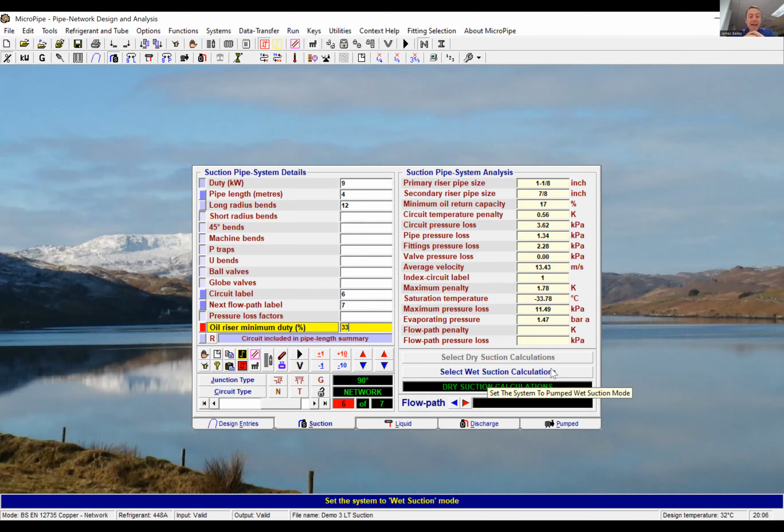Well, in some respects, that's exactly what we've been doing this evening as well, because I become quite pedantic when I'm using the software, Trevor. If I had a UK designer next to me, they would probably roll their eyes at me when I'm selecting double risers in this instance, because they know, like an install tech, let's just put a single in. It's going to be a cheaper install, and we're always going to get that oil back.